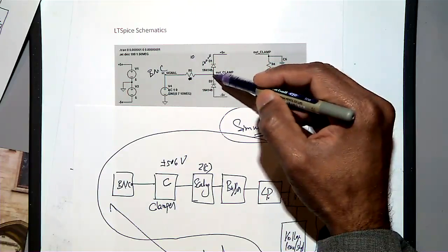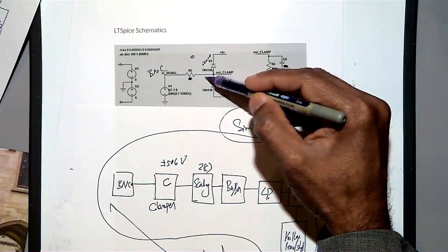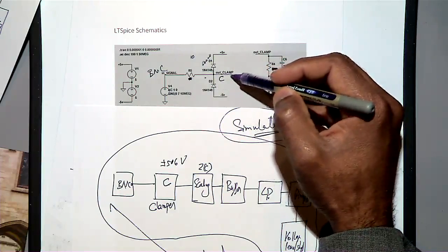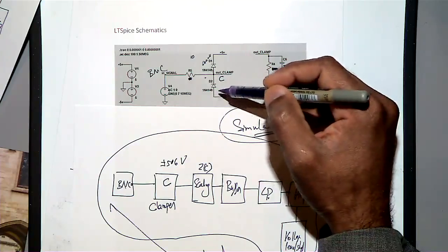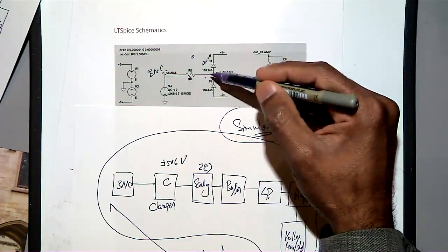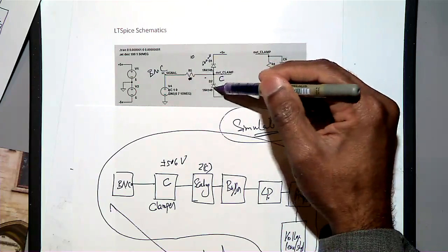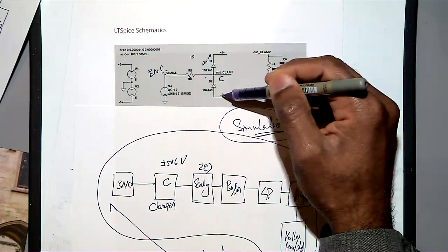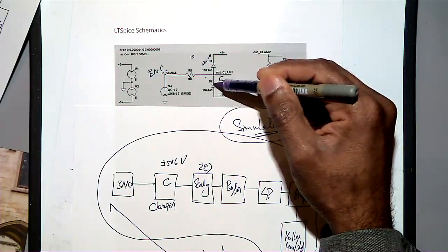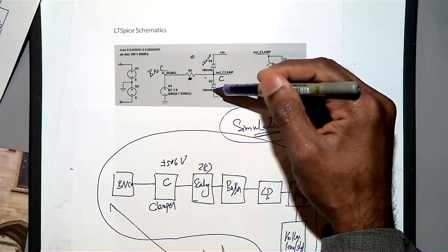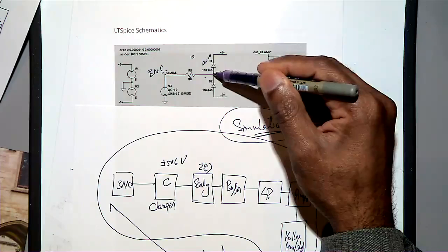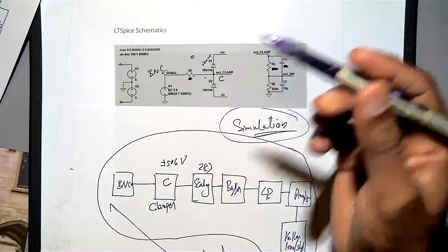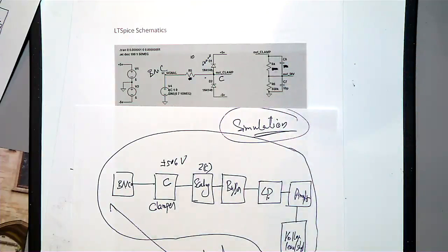When it is 4 volt, what will happen? When it is 4 volt, this diode will be reverse biased, nothing will happen, it will go through this to here. Again, when it is minus 10 volt, somebody touched here minus 10 volt, what will happen is this diode will be on, and then it will be shorting to this minus volt, and then here again you will have 600 millivolt drop. So this point will not exceed, because of two diodes, plus or minus 5.6 volt.